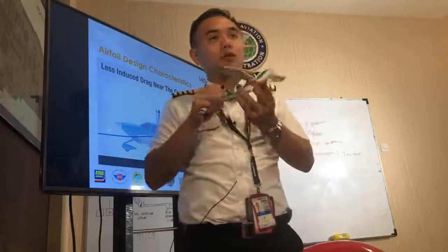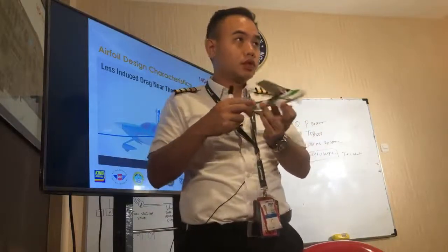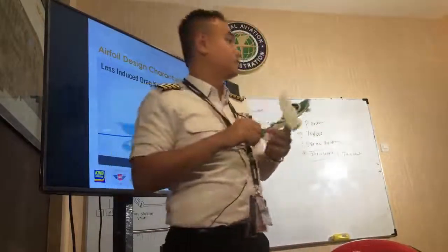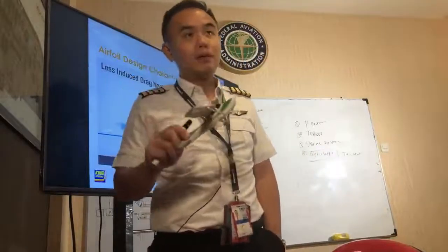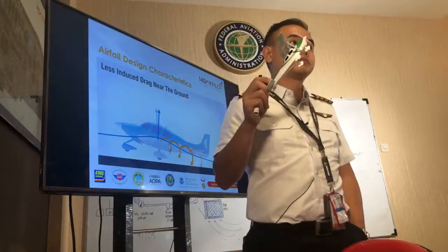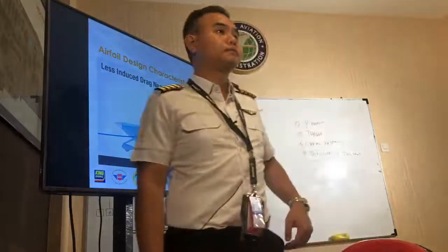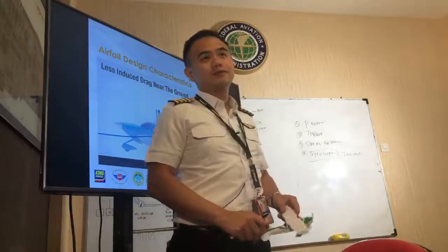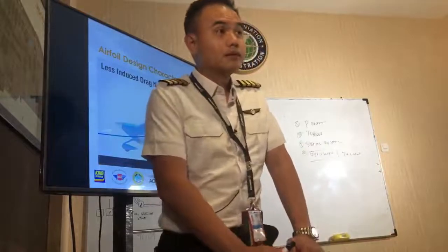So what kind of force do they produce? Yaw. And how do you compensate for that? Use right rudder. And when it happens: high angle of attack, high power, and slower speed. Right? High angle of attack, high power, slower speed. Now, torque. What is torque?